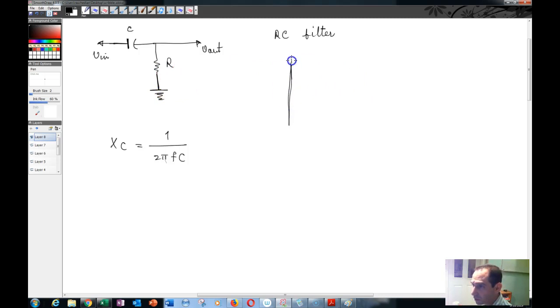So then you would have some situation like this, where you have your F of in here and V of out, and this is, by the way, also V of R, basically the voltage across the resistor. And as you increase this frequency, the voltage across the resistor is going to increase up to some level very close to your supply voltage, and then it's going to level off here, and then it keeps going in that direction.